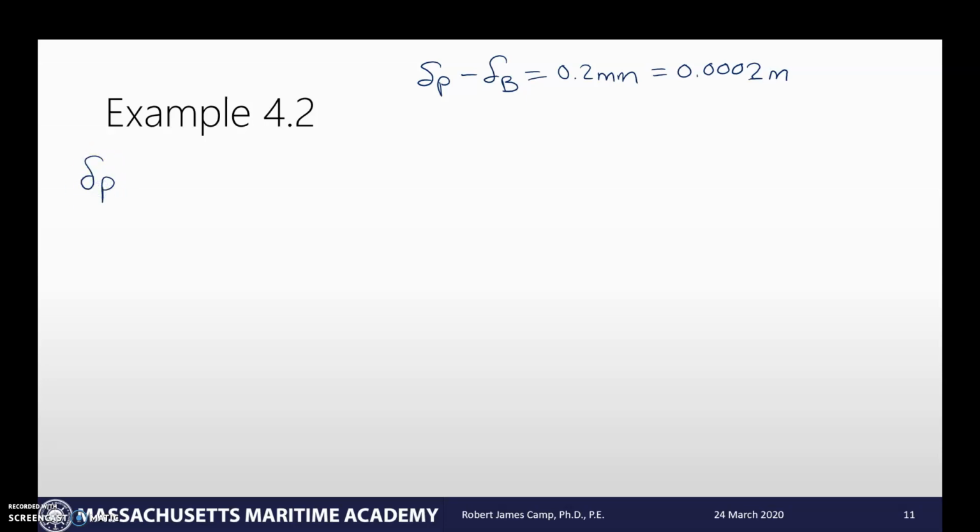So the deflection of P, that first load, is PL over AE. So if I look at it, P is that load of 20,000 newtons, because now that we're ignoring that there's anything on the other side, it's statically determinate. We can just go, okay, well, that's 20 e to the 3 newtons. The length over which it acts.